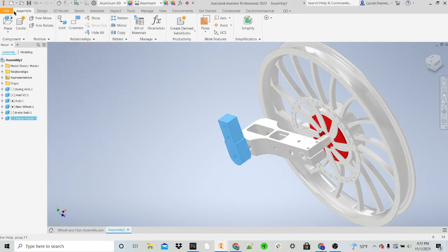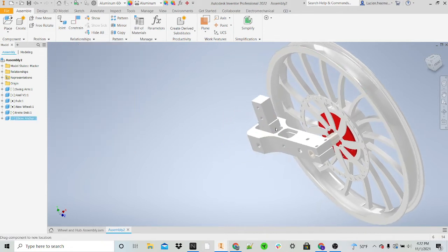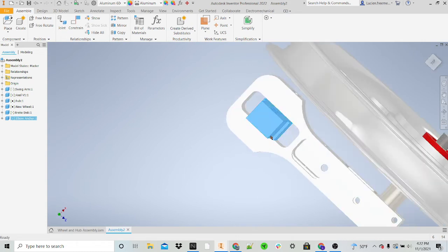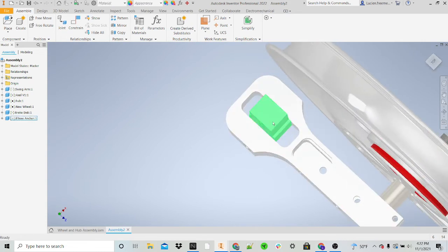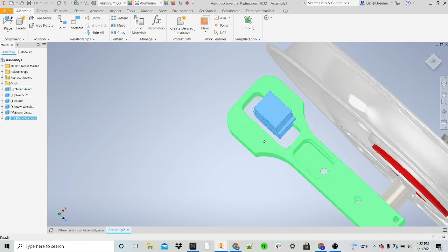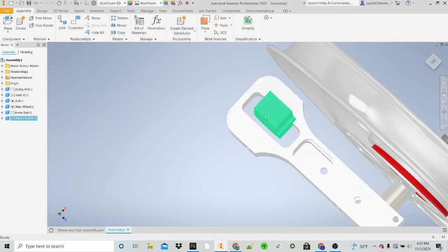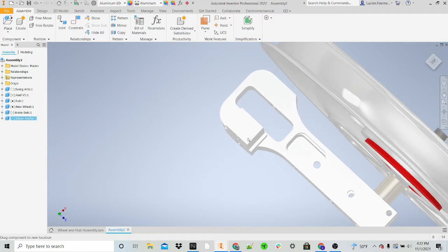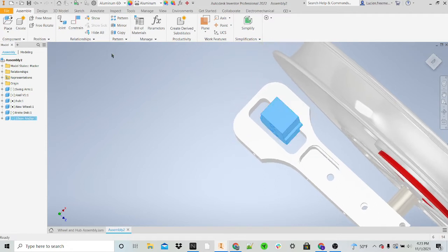either side. So what I'm going to do here is I'm going to move this so it's just on that side. Eventually I like to be a little bit picky sometimes about this because if I say 0.03 or 3/100ths of an inch, it's going to take it to the shortest distance. So it's going to be on this side if it's over here. It's going to take me to 3/100ths on this side if I'm over here. So I want it on this side.